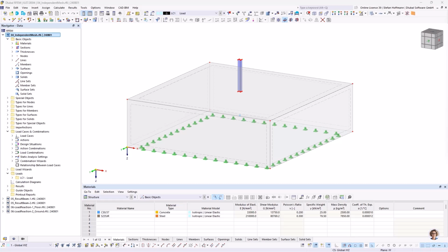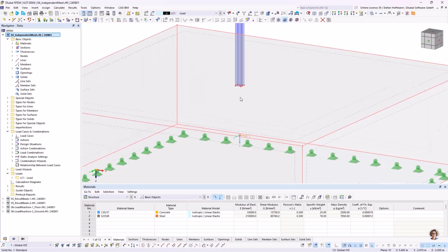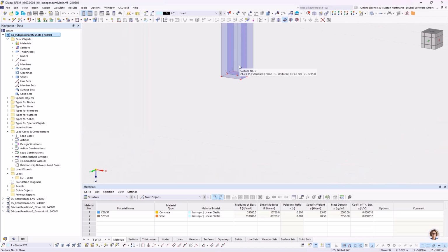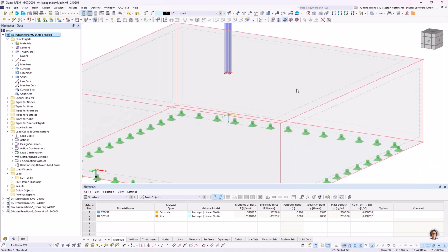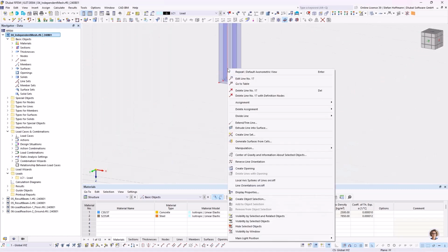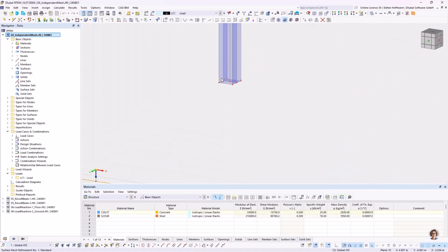So the next question is, can I generate the FE mesh of two or multiple objects independently? This question usually arises if you have a big solid which can, for example, represent the ground, and then you have a girder or a beam connecting to it, represented by surfaces, and a fine FE mesh of these thinner surfaces next to the solid, because we propose that the solid mesh should be at least 4 up to 8 elements per thickness. It may of course be even finer.